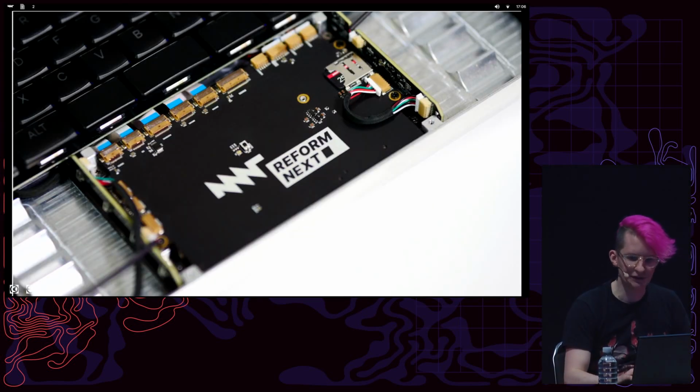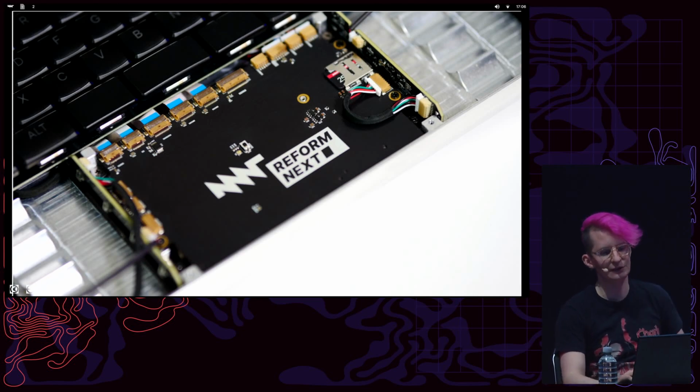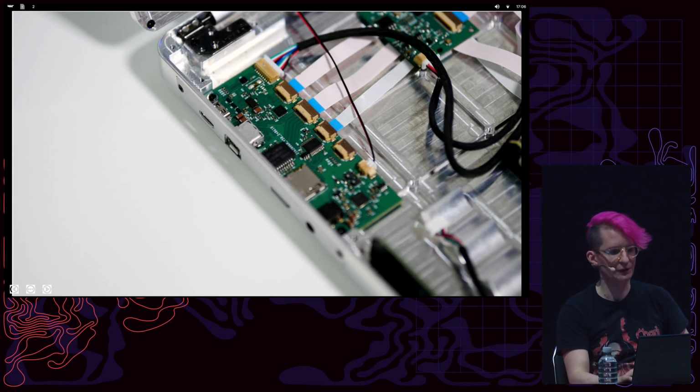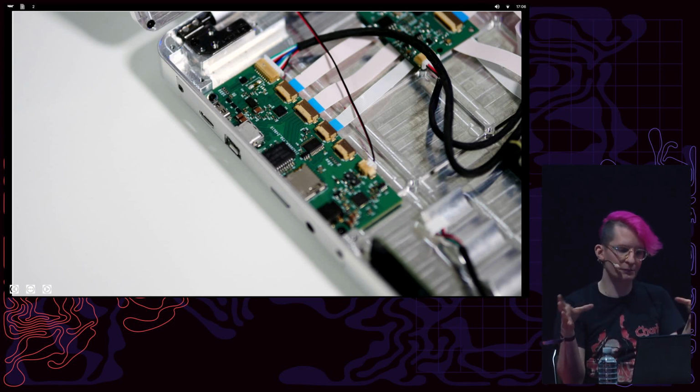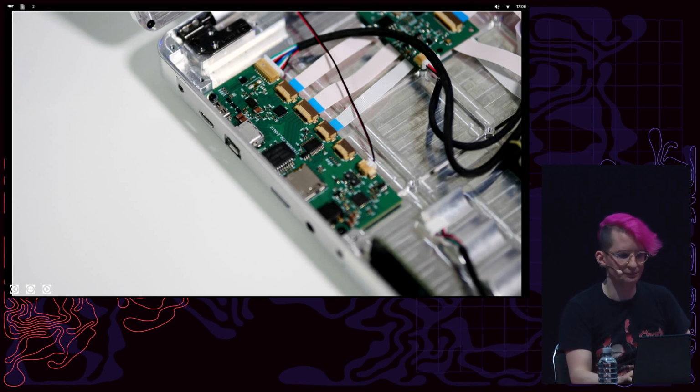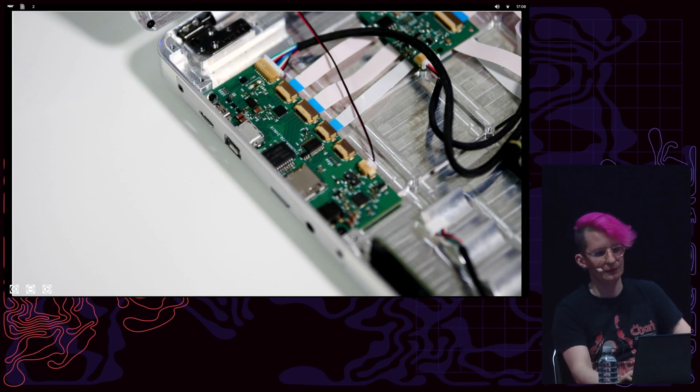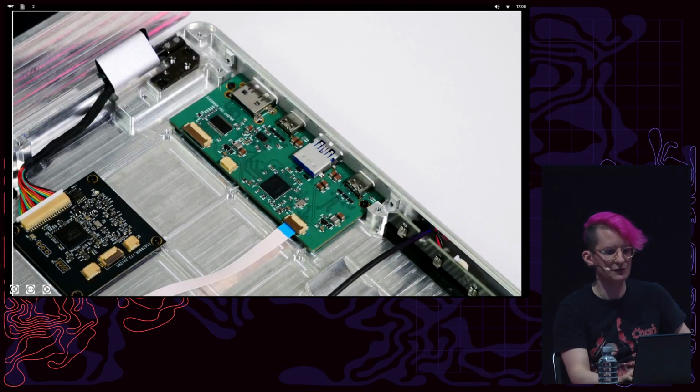To achieve this, I sacrificed the acrylic bottom plate and the trackball and split up the motherboard into a lot of smaller PCBs that are spread out all over the main body of the laptop. The motherboard is now much smaller and fits upside down on the trackpad and between the 2 battery packs. The processor is cooled by conducting heat directly to the massive aluminum bathtub design of the main body. I also remembered the Novena laptop, one of the inspirations for Reform, and so we put a 40 millimeter spaced mounting grid under the keyboard where you can mount your own electronics.